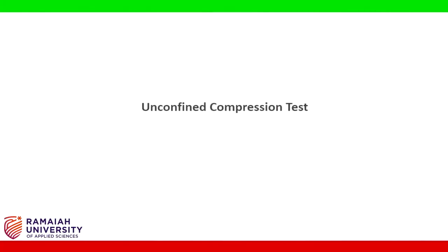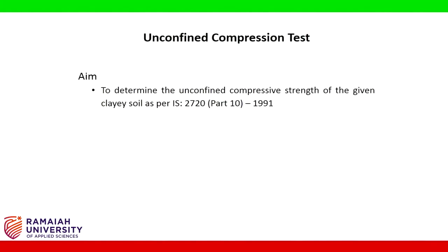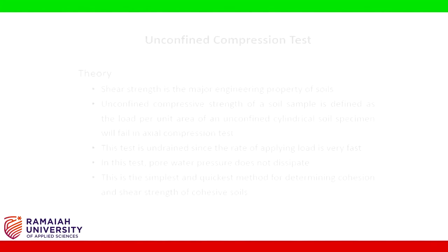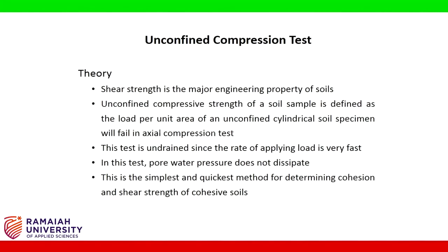Hi students, let us discuss unconfined compression test. The aim of the experiment is to determine the unconfined compressive strength of the given clayey soil as per IS 2720 Part 10 1991. Shear strength is the major engineering property of soils.